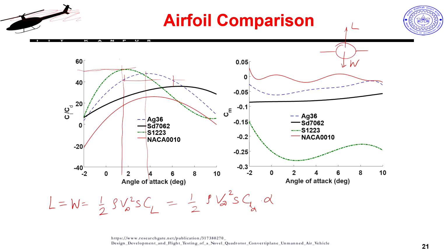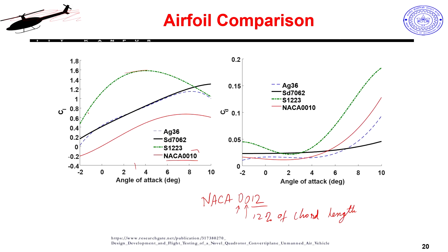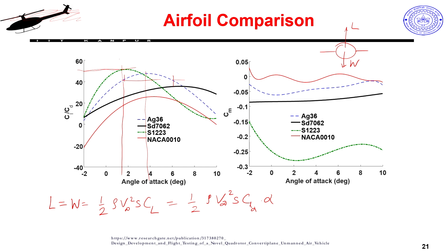For small angles of attack it will be like that. Okay. So you can see this is fairly linear, although this area is non-linear, remember that, the maximum lift area, and this also has a fairly linear profile. So, I will take that as CL alpha into alpha. So, I will get the slope of this graph. So, I can write it like that, right.